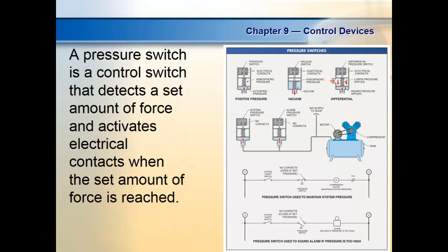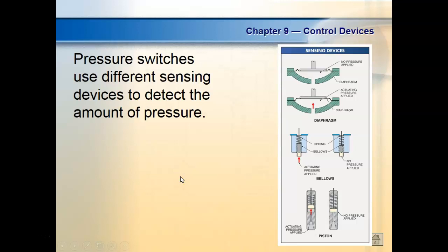This is a 4-wire sensor, so it's got a white wire, which would be a normally closed contact. So the black represents a normally open contact. If we got a single pole double throw, then the normally closed would be white. So we have 2-wire sensors. These are devices that actually power stuff through the load. These guys are using high voltage sensors, where we can afford the drop. We have 3-wire sensors. These guys are usually operated at lower voltages, and you have to power them up. Right? You understand that? And we have what we call a 4-wire sensor.